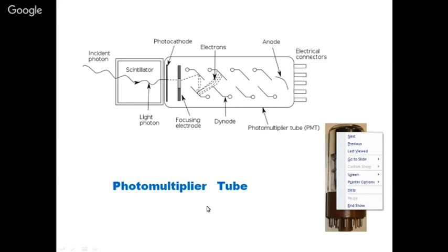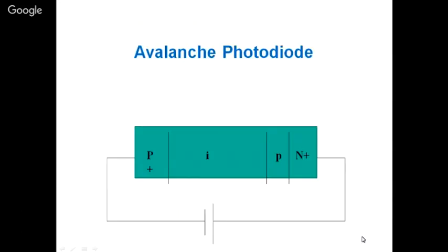So they said, when we can do this, can't we do this in solid state? So they have come out with detectors. They have come up with the avalanche photodiode, which is also P, I, P, and N. They have added a layer into this, and now this is able to give us avalanche. So even less than a picowatt, you can detect.